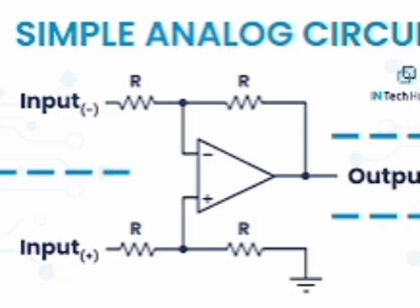Early effect, also known as base width modulation. Due to early effect, in common base configuration the common base current gain increases, emitter current increases, and punch through or reach through occurs. The output resistance R0 equals VCE plus VA by IC, where VA equals early voltage.